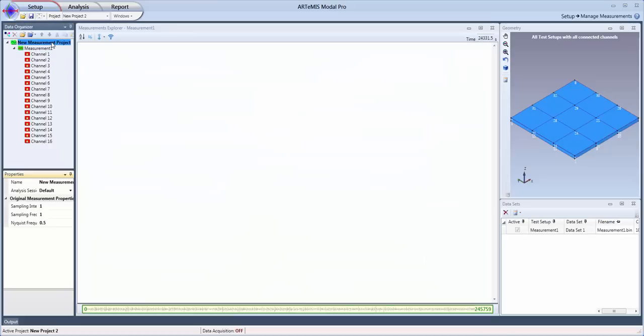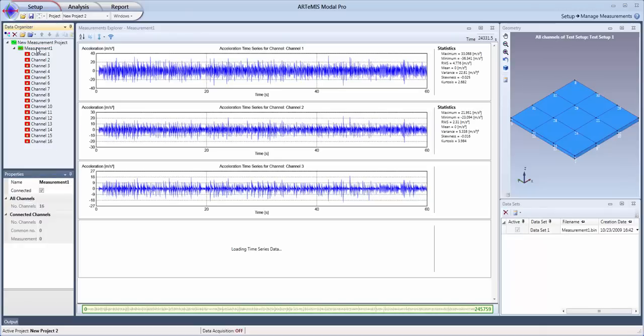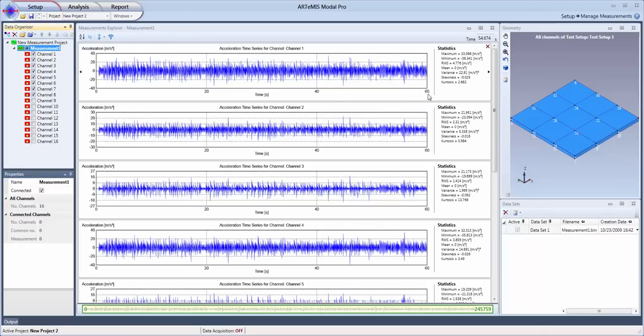So what we do is insert this by clicking this parent item again. Now we can insert either the Nyquist frequency, the sampling frequency, or the sampling interval, depending on what we know. I know that the Nyquist frequency is 2048 Hertz, like this. And when I go back now to the data, we can see that we have up to 60 seconds of data, as expected.